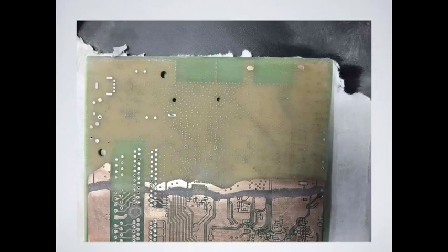The idea is that we would take the picture and there would be several layers, right? Then you had to write the program and the algorithms to match up those through holes. Once you match up the through holes, you're supposed to be able to connect the net list. There's going to be a net list for each layer, and you take those net lists and automatically figure out which one's matching up to which.